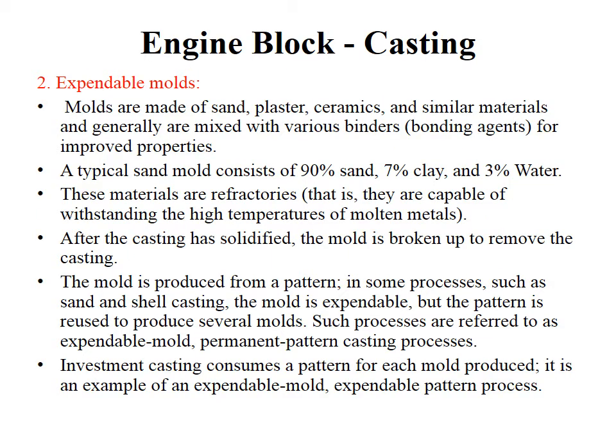Next come the expendable molds. As I already told, expendable molds are made of a material which will be destroyed at the end of its use. Molds are usually made up of sand, plaster, ceramics, or similar materials which are bound together, and a sand mold typically consists of 90% sand, 7% clay, and 3% water. All these materials should be capable of withstanding high temperatures, and they are known as refractories.